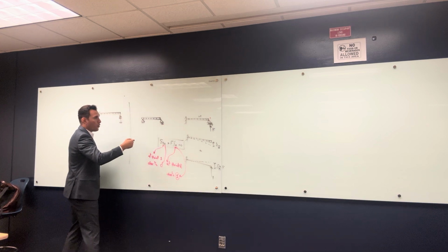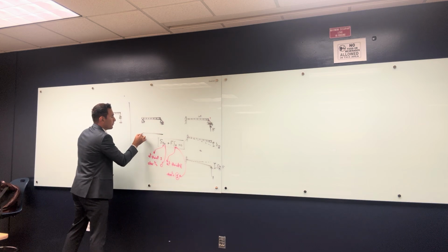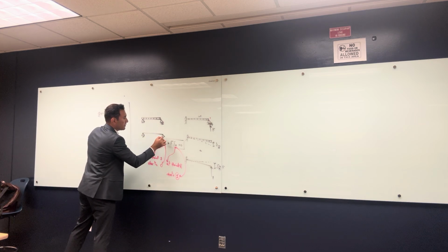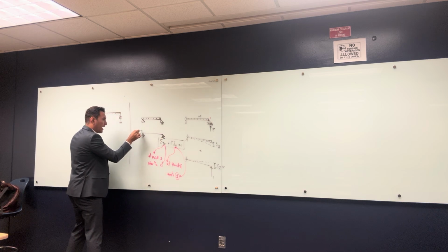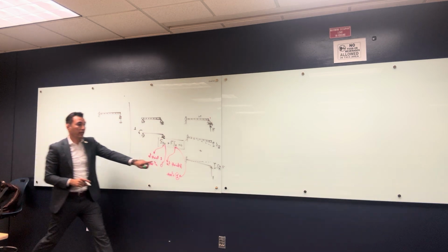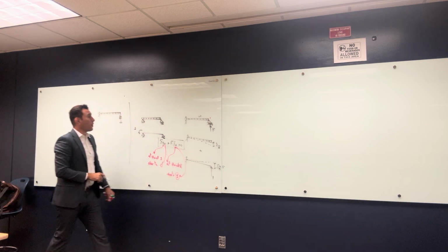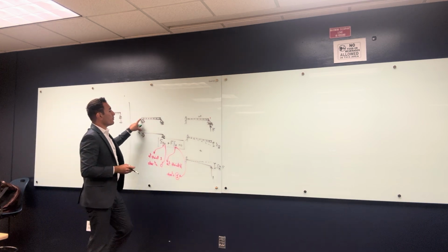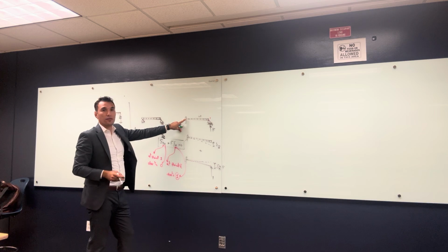So when you remove the moment, so that second beam is gonna be something like this. And then you put the unit load, 1 unit load here, rather than here. Because here I said that I released, like here theta is 0, right?